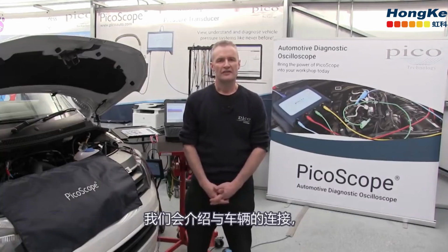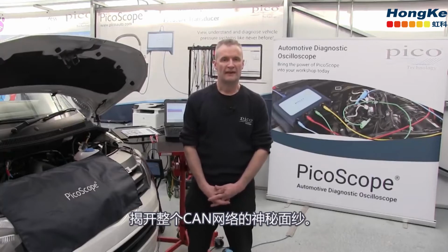Welcome to the next part of our presentation, looking at serial decoding within Pico. Now this is going to look at connection to the vehicle, setup of the scope, application of serial decoding, math channels, and then just how much information can you pull out from serial decoding? What is there of real use to us as technicians? Can we decipher what computers are online? Just generally break the CAN down, demystify the whole CAN frame.